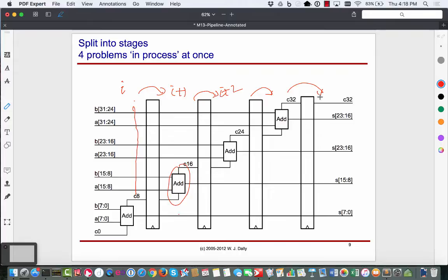So on the face of it, it seems like a bad deal. What I was doing in 1 clock tick, I'm now doing in 4 clock ticks. Granted, while the original pair was being handled by stage 2, I can begin to process the next pair. But it sounds, looking at this from just a single pair of numbers' perspective, as if it's now taking 4 clock ticks.